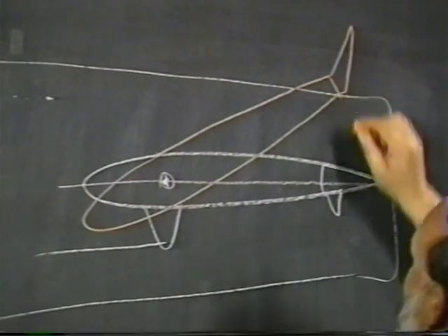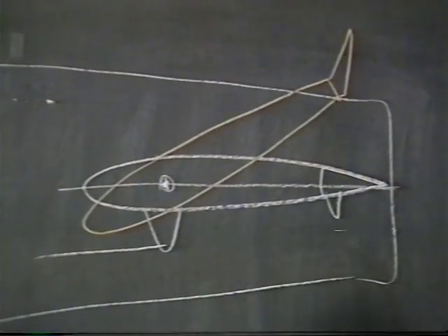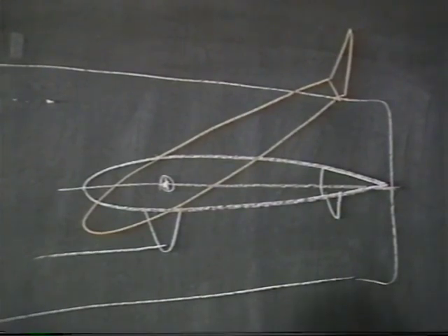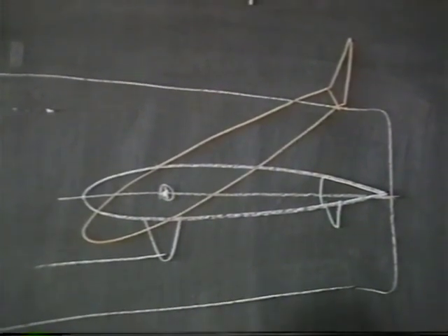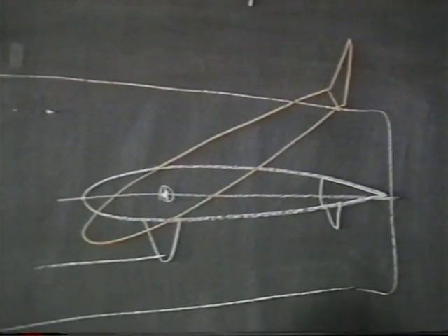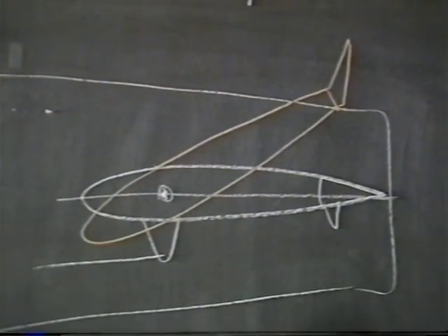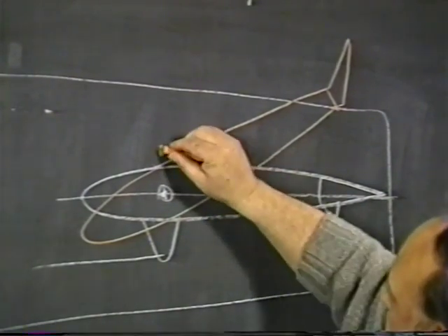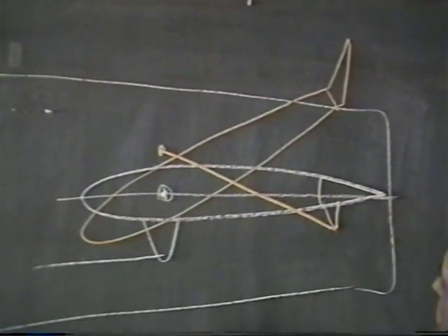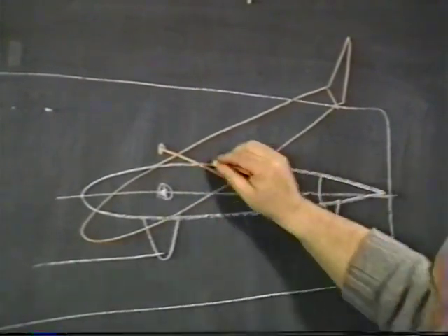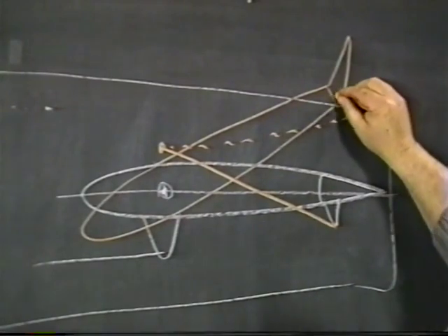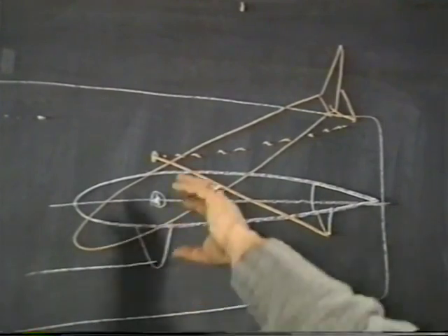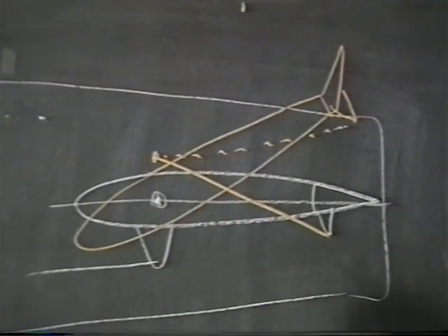So you make it so that the surface, this little servo tab or anti-servo tab, because the definition of a tab is this little surface in the back. If it helps you move, that's called a servo tab. If it fights your movement, then that's called an anti-servo tab. And in this particular case, that's what it would be. You normally do that by finding a spot somewhere above your quarter chord and hooking your structure to that. And so as it moved here, it will push this surface up. This is sort of one way of looking at it. And then as the tail came down, it would move the opposite. So now you have both.